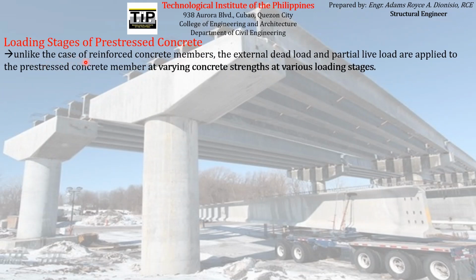So unlike the case of reinforced concrete members, the external dead load and partial live load are applied to the prestressed concrete member at varying concrete strengths at various loading stages. For reinforced concrete members, the ultimate loads that are anticipated to be carried by the member are applied usually at a specific concrete strength, which is the 28-day compressive strength of the concrete.